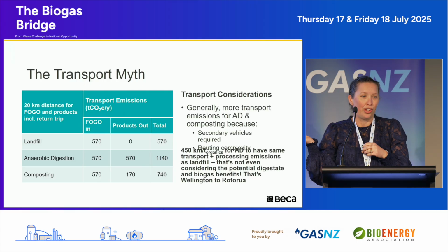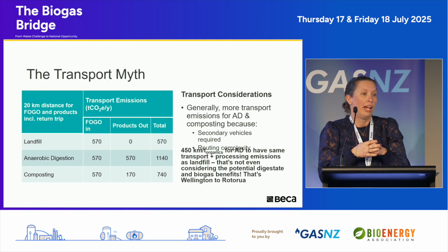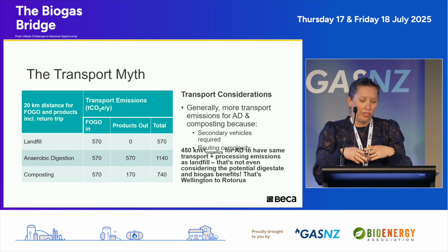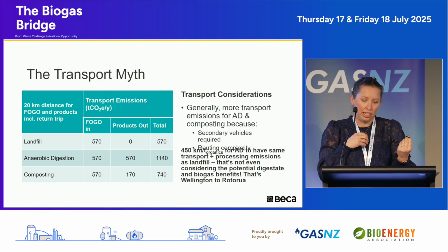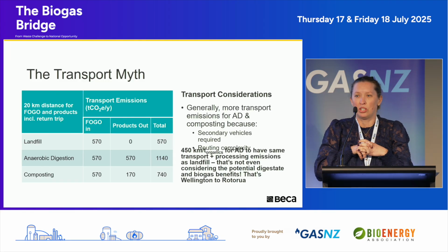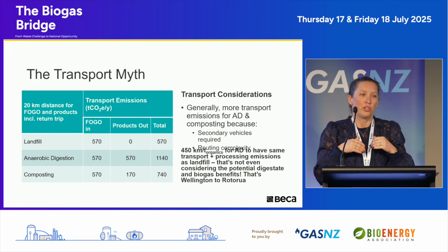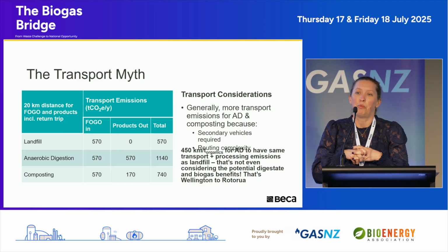But if you remember the 30,000 tonnes of emissions that we had from landfill that were just the methane escaping from the landfill that we don't capture, the extra few hundred tonnes that we've got of transport actually doesn't stack up from a carbon point of view. It doesn't have the same level of impact. If you want to get the emissions for transport for organics somewhere close to the same level as landfill, you could transport it hundreds of kilometres before you're getting to the same level, which is where you can say the transport myth from an emissions point of view is not the big deal that we think it is.